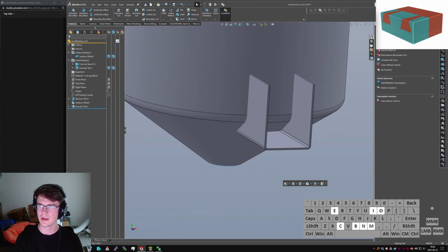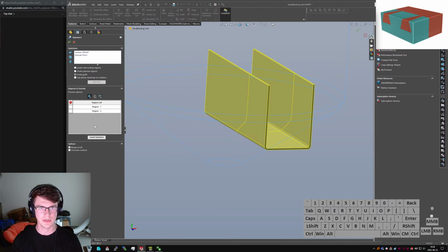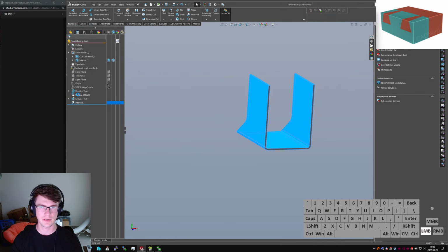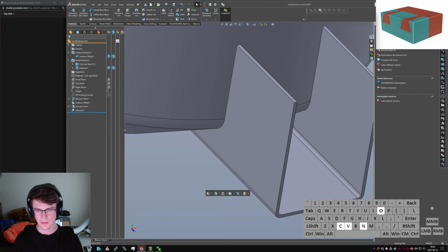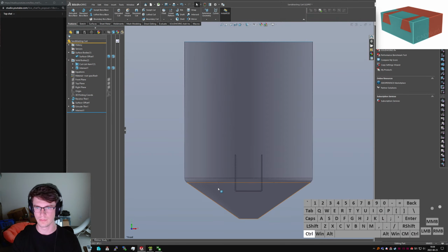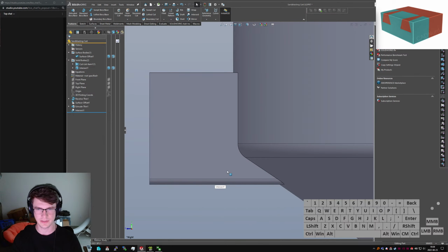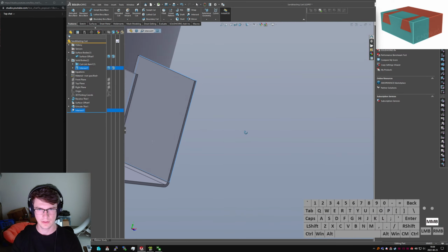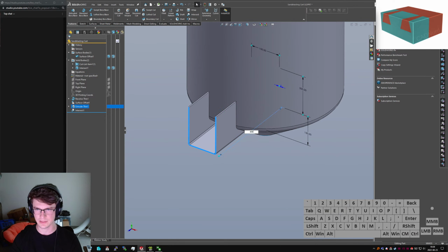Okay, now we can use an intersect. And intersect, consume surfaces. Actually, maybe I don't want to consume surfaces. Maybe I need this later. Yeah, don't consume that surface. Convert to sheet metal, or here's what we'll do. We'll come from the side and trim some stuff out of the bottom too, just so that it's a little more accurate to what the finished part was. I think maybe I even want to extend that a little, so let's make this 600 or 550.